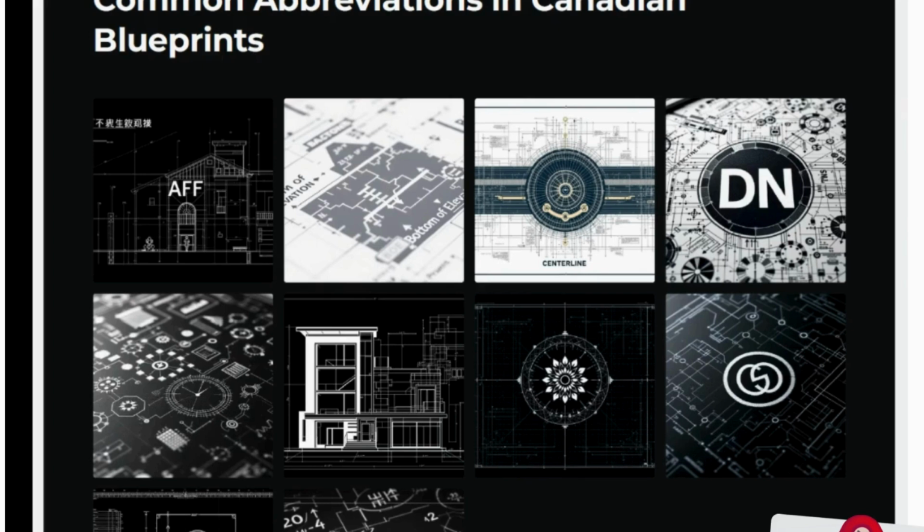All the previous explanation of the blueprints, whether it's about the drawings, the idea of the drawings, the criteria of the drawings, can be common between all countries. You start studying them in college, but when you reach the abbreviations, this is where you have to start focusing, because the abbreviations in the blueprint are the unique part. And if you understand them based on the abbreviations in your country, you'll have a misunderstanding of the drawings.